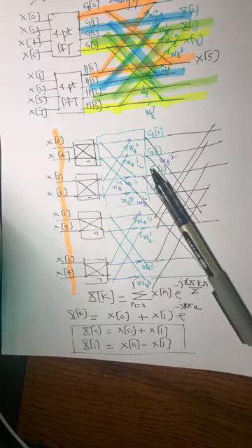As a matter of fact, instead of calculating 1, you can perhaps calculate 100 of those DFTs if you use this algorithm. 100 times faster, even perhaps for a 1K point DFT computation. So the fast Fourier transform has really transformed digital signal processing. But if you go and look at it, it is such a simple trick which Cooley and Tukey used.